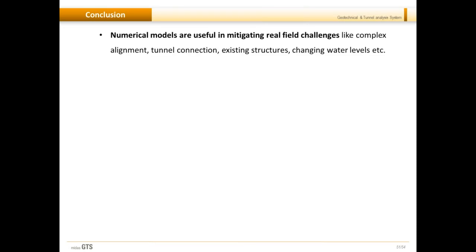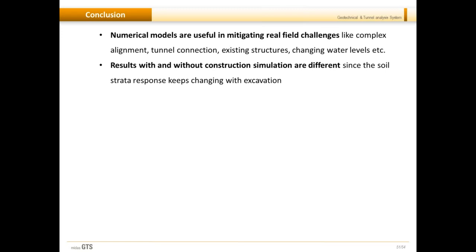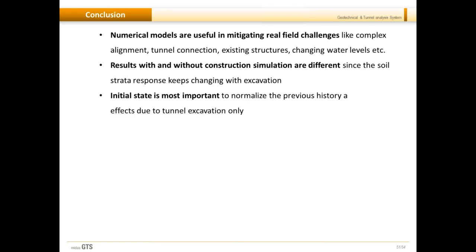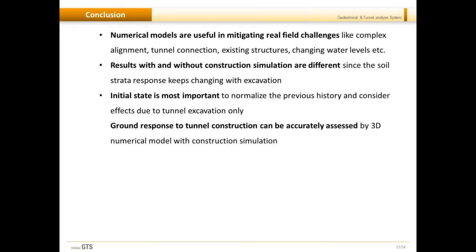So this brings us to the final part of the presentation, where I will be concluding the things that we have learned so far. So first of all, numerical analysis is useful in mitigating real field challenges like complex tunnel alignment, tunnel connections, existing structures, and changing water levels. The results with and without construction stage simulated are different, since the soil strata response keeps changing with excavation. Initial state is most important to normalize the previous history and consider the effect due to tunnel excavation only.